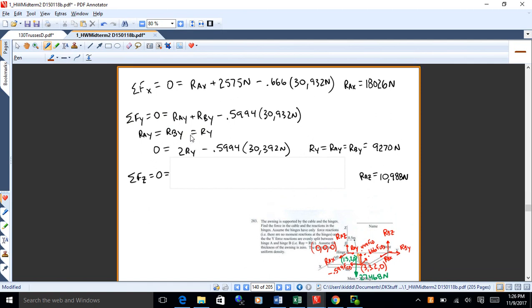All right, and then to finish it off, you have to find the forces at A and then that one remaining force at B, which is RBY. You are given that RAY is equal to RBY. That's part of the problem statement, so you just assume they're equal. You just do a sum of FY, and RAY equals RBY. So you can just do force equations to solve for these last ones.